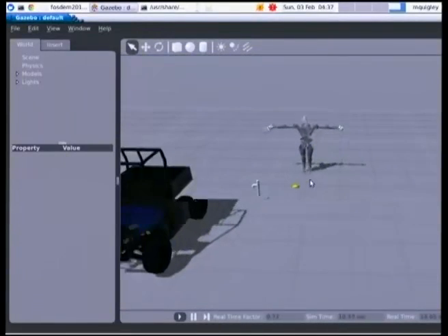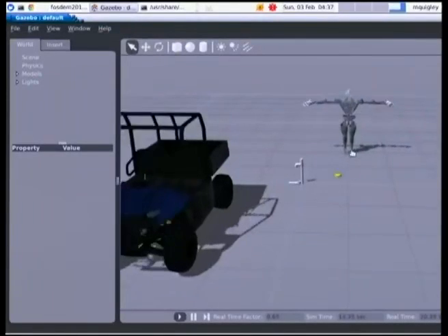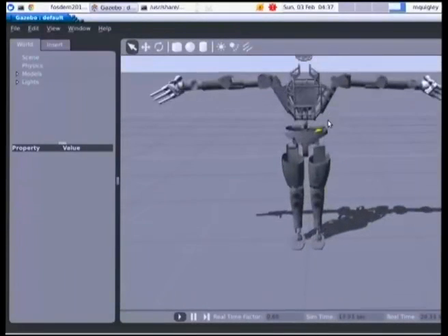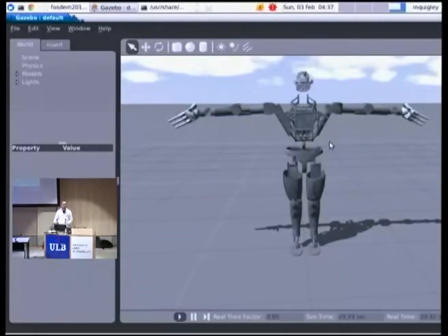Okay, so the interesting and fun thing now is that it's not just a cartoon, there's actually rigid body dynamics running here. This is actually a physical simulation. So you can see the robot is a little bit wobbly, looks a little teetery. That's because there actually are position controllers running, trying to hold that posture. And you can see them waving around a little bit. We just wrote a very, very simple controller as a straw man. We're expecting, of course, everyone to throw away that controller that we wrote, but use the underlying infrastructure and simulation engine to write their own software.